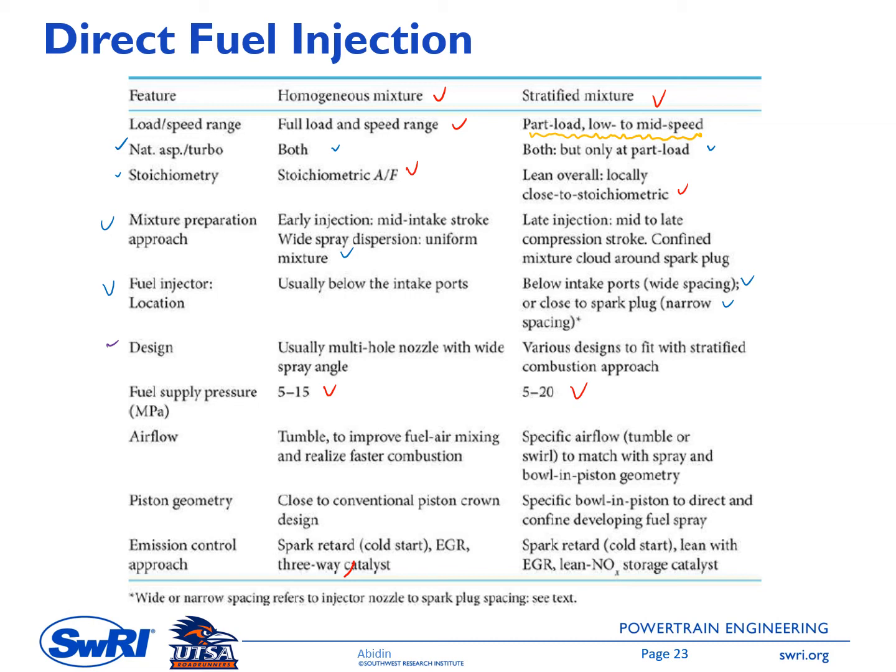Latest research by Southwest Research Institute shows that a higher injection pressure still gives a benefit for GDI. Last year we did research looking at 500 bar injection pressure, and we did see an improvement in the engine PSFC.